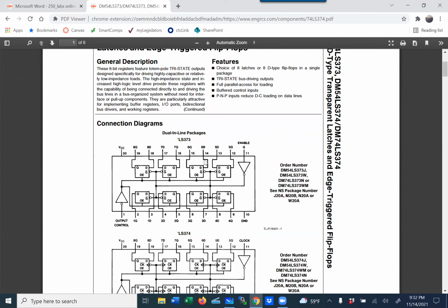In other words, you can go ahead and do the state diagram, and then the next step, go through and do the present state, next state table, and then do the schematic based on those, much like we learned in the classical design of synchronous machines. It just takes a lot longer to do that.